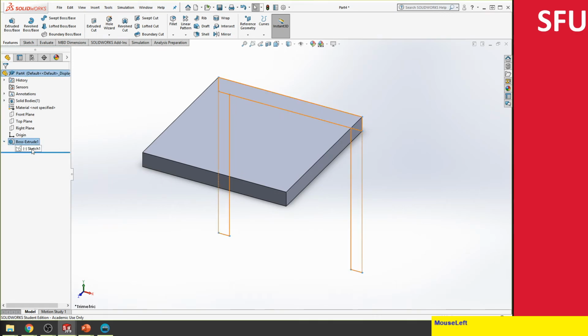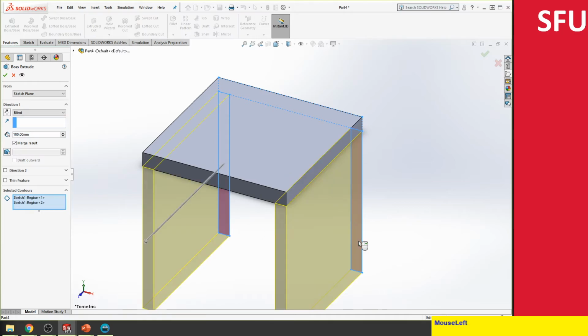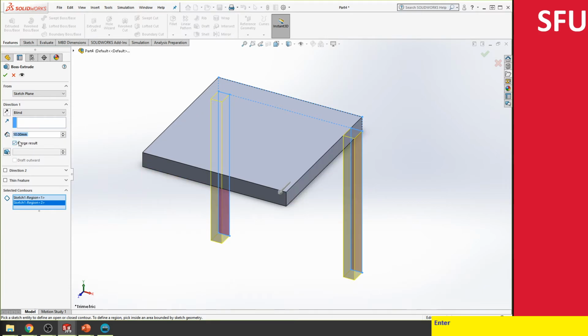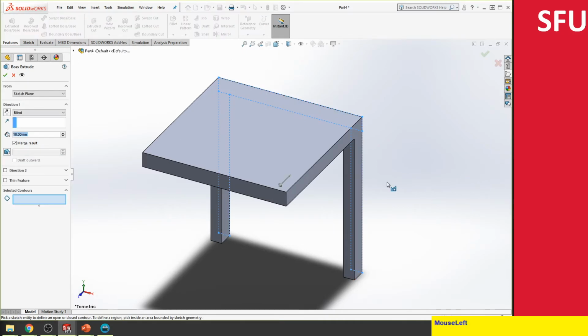So we're going to select again and then select the leg regions. So this we want only to be about 10 millimeters. And then set the value to be 10 and then say OK. So what I can also do is select the sketch again and then say extrude. But now I can do a couple of ways. So let's do